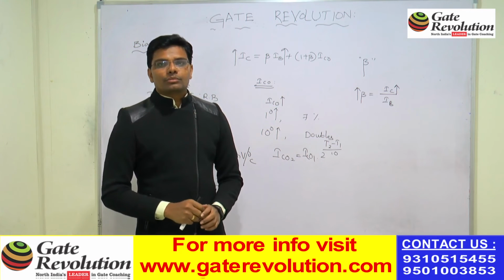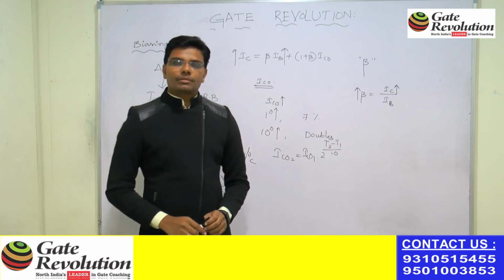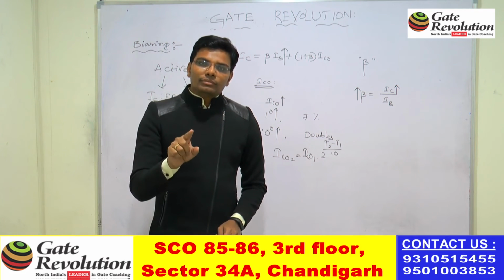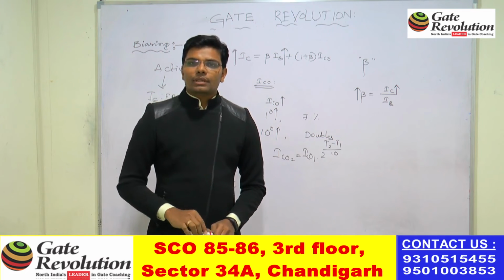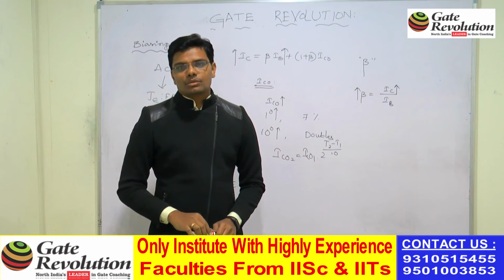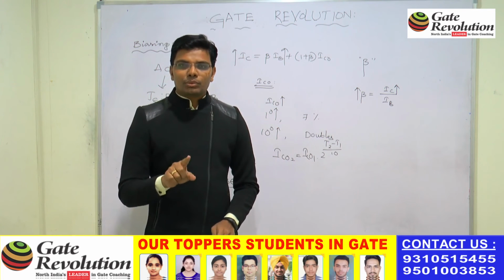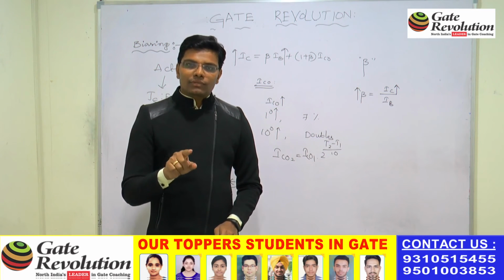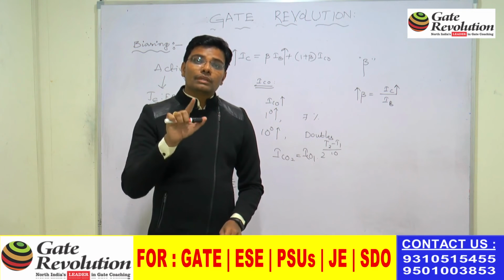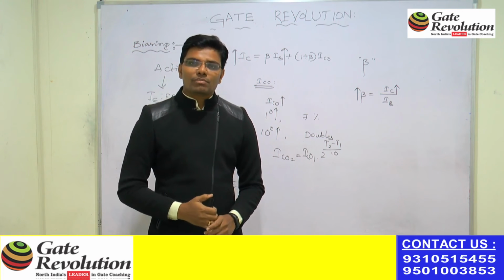I would like to raise two questions, only two questions. One question: if temperature is affecting ICO, VBE and beta, then by using the biasing circuits we can stabilize the operating point. Suppose temperature based components are trying to change the operating point positions, then what do we have to do in the amplification process?